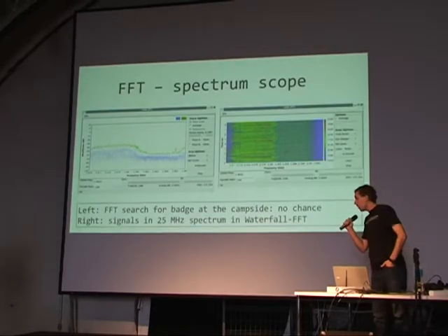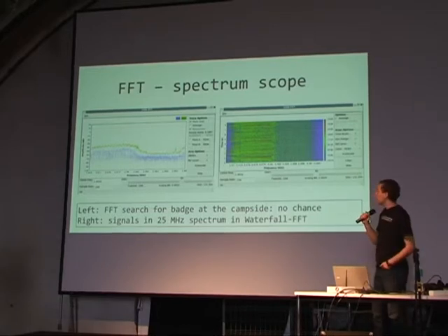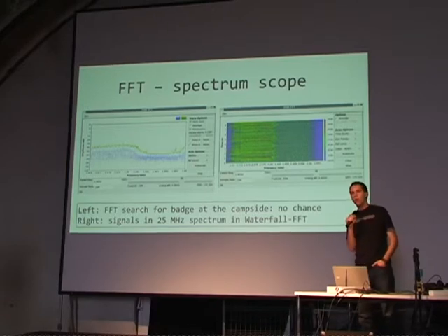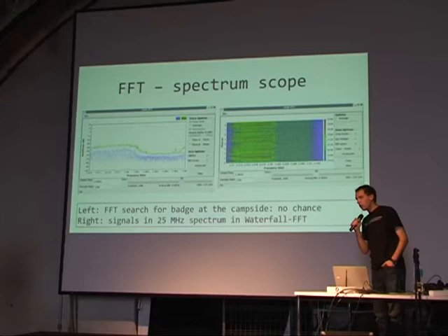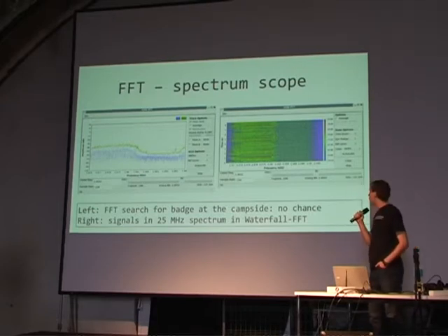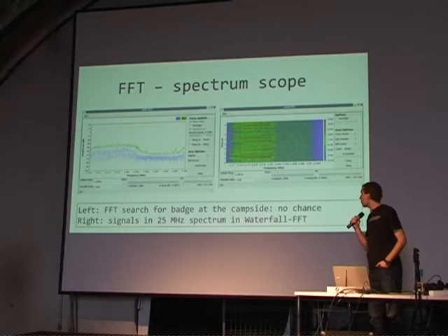So as I have shown, the FFT takes a peak and therefore defines where a target signal actually is within the spectrum. So within the ISM band, as I mentioned, there is a lot of stuff going on, so it's a little chaotic and disorganized. What we see to the right is a waterfall plot that practically logs over time what kind of peak occurred.